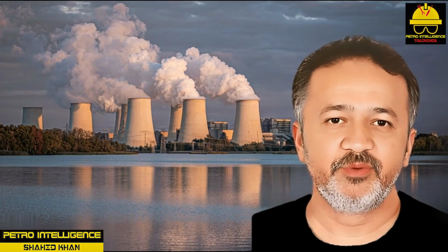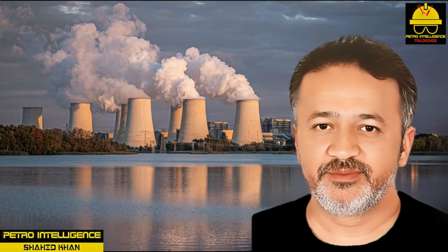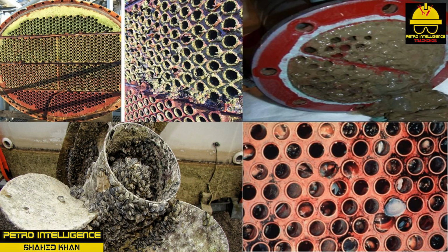Microorganisms, chlorine and bromine concentrations. Cooling towers provide the perfect breeding ground for microorganisms since they are exposed to warm water and sunlight. Microorganisms form slime that can build up and restrict water flow and conductive heat transfer. Biocides such as chlorine and bromine can control the growth of these organisms. Unfortunately, chlorine is an extremely hazardous material and must be handled with caution. Bromine is a little safer to handle and use.